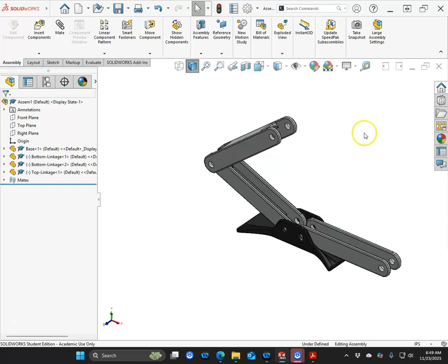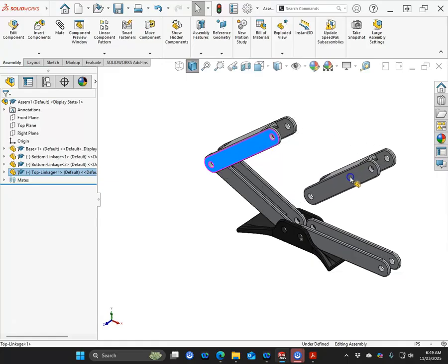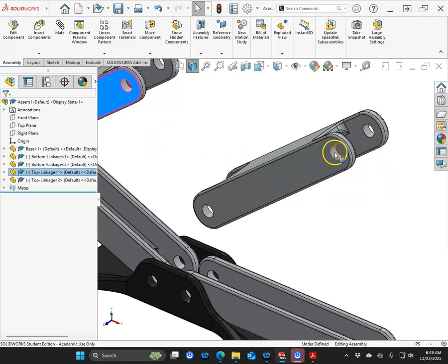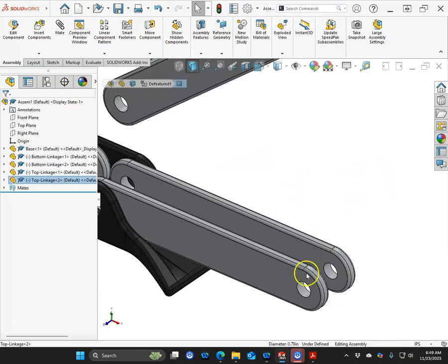All right, so we did the control drag from the features, from the components. Let's select the component in the work area, and this is the one you have to be careful of because you will have components start popping up. So we want to control drag and let go, and then we can go ahead with our mates.